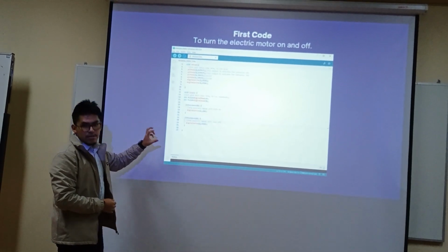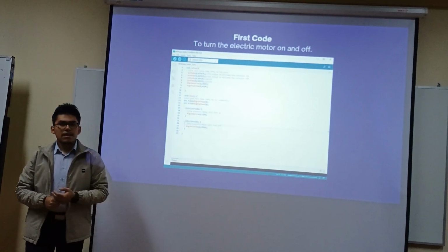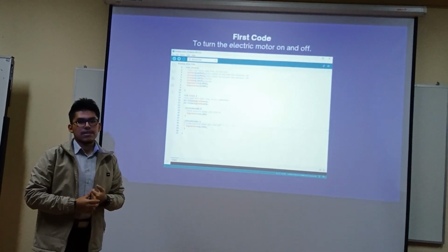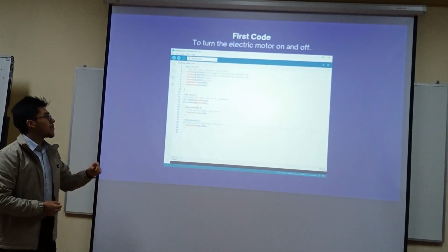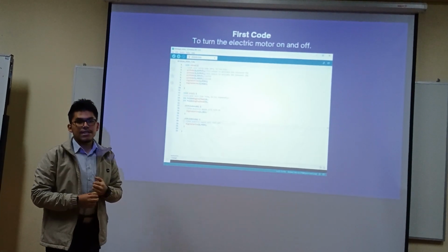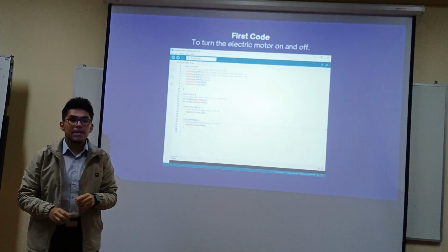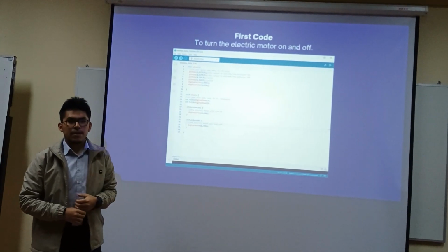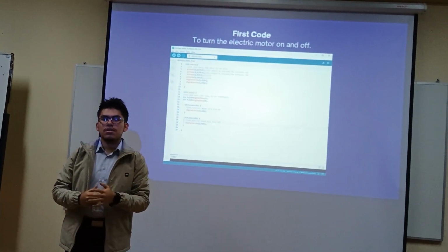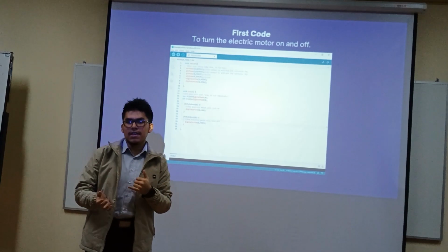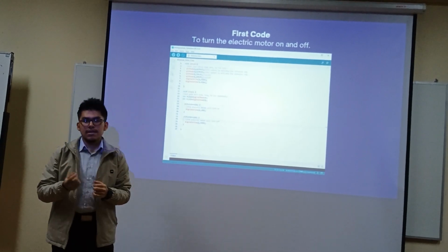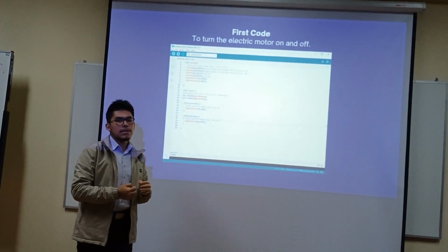You have two parts. First, the setup function. In the setup function, I configured the pins. For example, pins 2 and 3 are set as outputs to activate the contactors KM1 and KM2 respectively. And pins 4 and 5 are set as inputs to read the state of push buttons pulse A and pulse B. Initially, both contactors are set to high to keep the motor off.